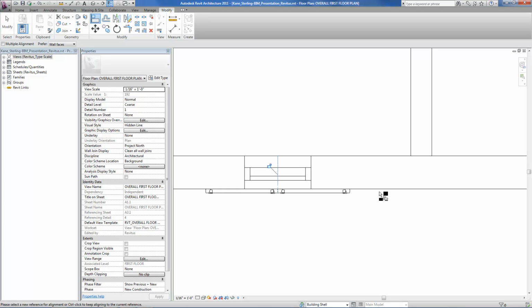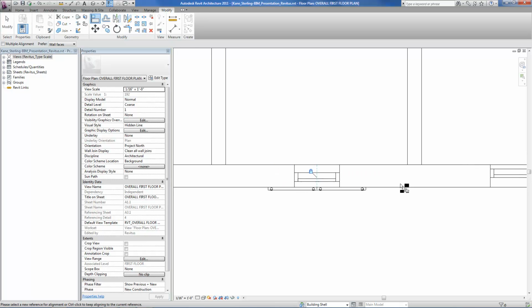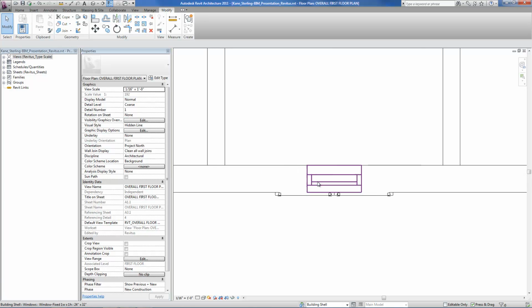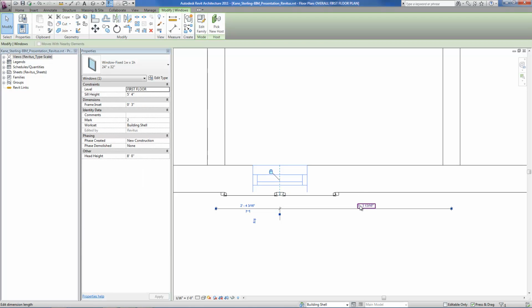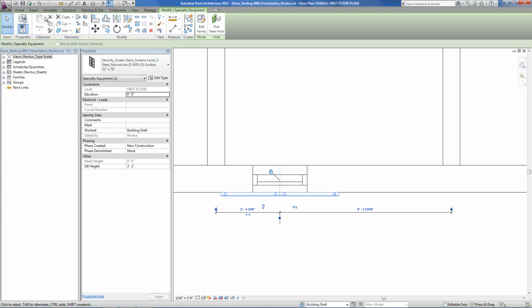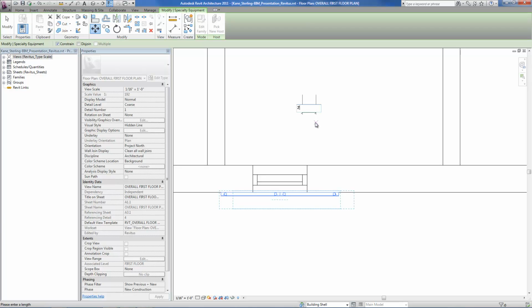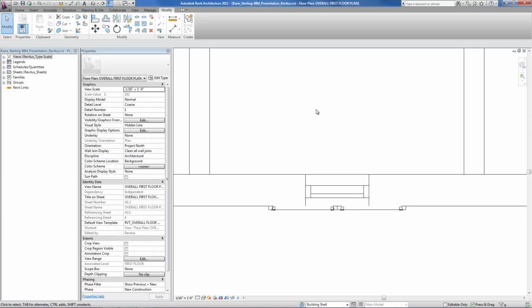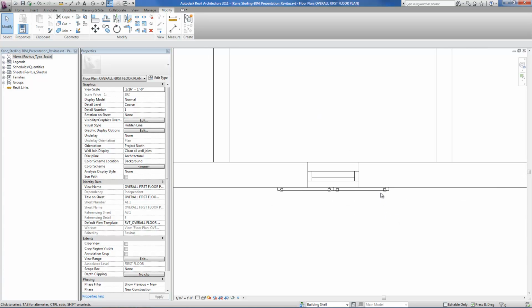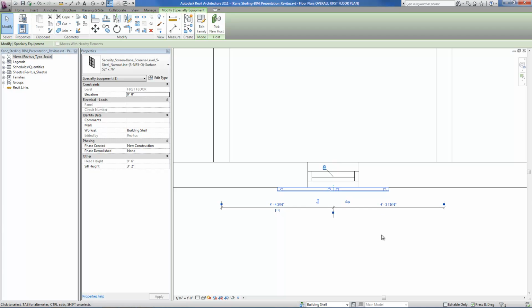Immediately after you align an object, a padlock icon will appear, giving you the option to lock or constrain the relationship between the two objects. Once constrained, moving either object will actually affect both objects to maintain the constrained relationship. Note that a Revit model can become over-constrained quite easily if the Revit user gets carried away with locking padlocks. Best practice is not to lock these two objects together. To remove the constraint, select either object and click the padlock icon again to unlock it.